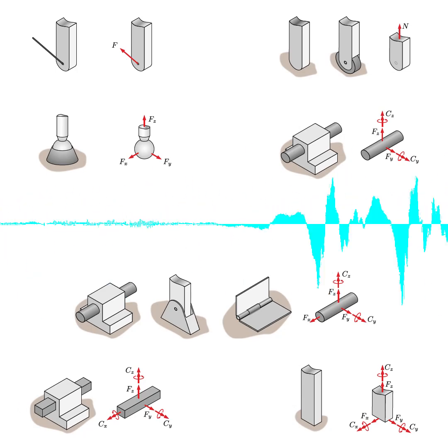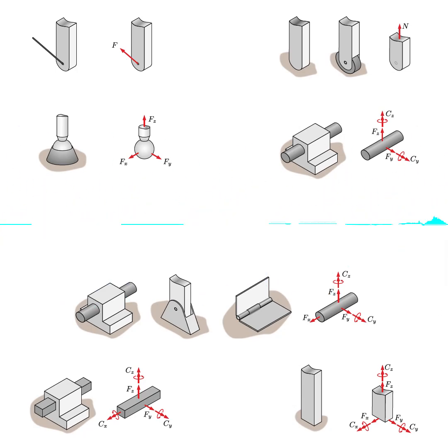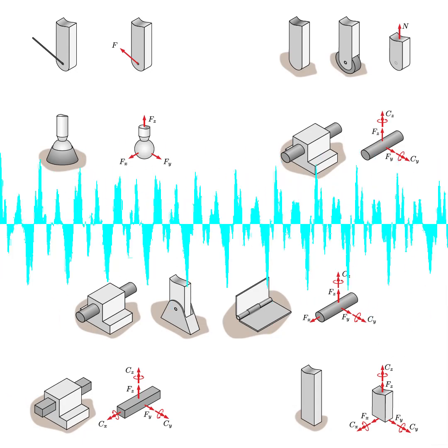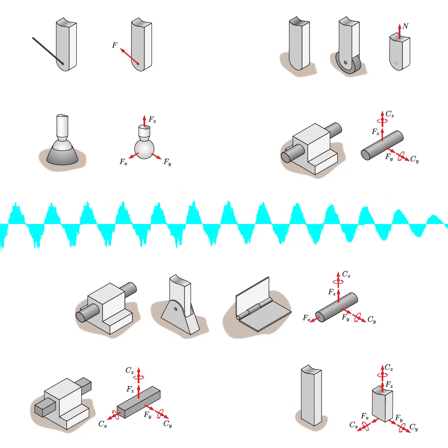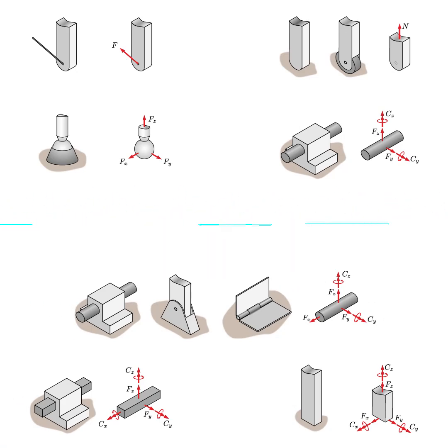So you have to kind of think in reverse and replace each support with whatever kind of force or moment it was preventing. Exactly. And figures 5.2.1 and 5.2.2 in the textbook actually show some really common types of supports and the reactions that they exert, which can be super helpful when you're first learning this. Yeah, that visual aid is definitely key for wrapping your head around it.